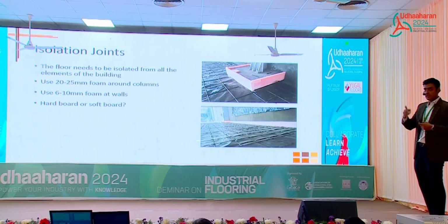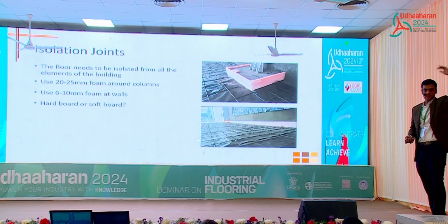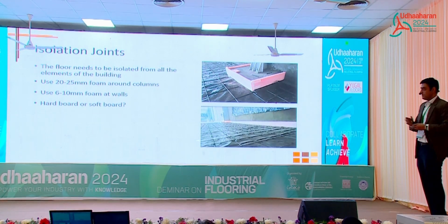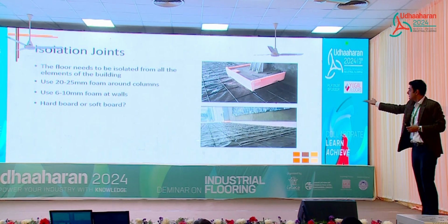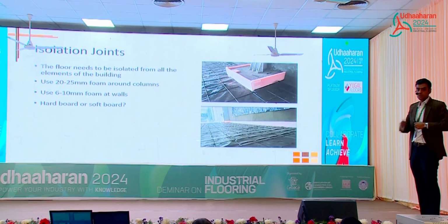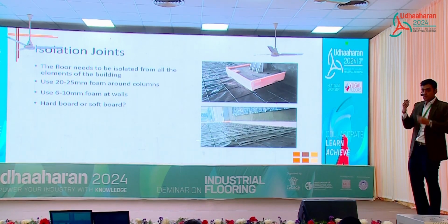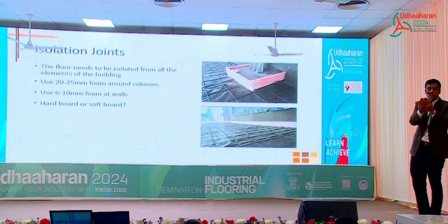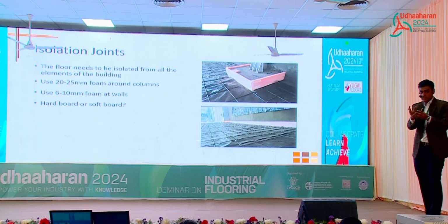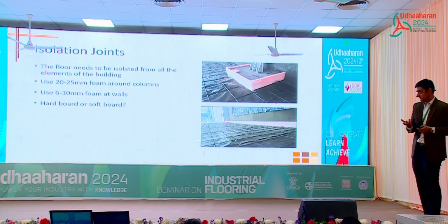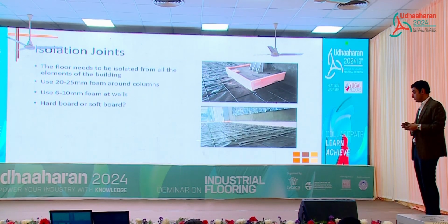What I have seen is that we give shear connectors in these slabs. Here, people also leave steels horizontally from the plinth beam or the walls. We actually go and get them cut. You should not have any connection between any building element and the floor element, because what you're doing is creating restraint. That restraint is going to result in cracking. So those things you should avoid.